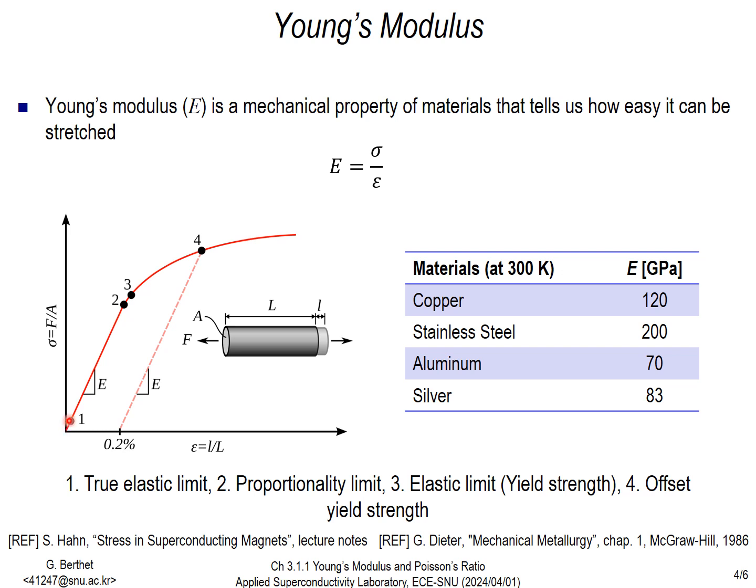From 0 to the point 1, we're in the pure elastic regime, so where we can use the Young's modulus. From point 1 to 2, the curve is still following a rather straight line, but strictly speaking, some dislocation will move, inducing permanent deformation, and therefore it is not considered truly elastic, though Hooke's law and Young's modulus are still usually used in this area.